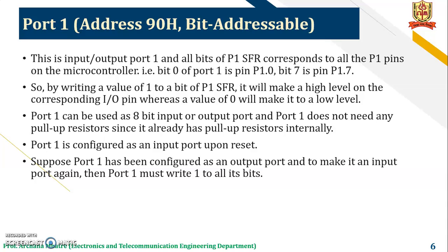So by writing a value of 1 to a bit of port 1 SFR, it will make a high level on the corresponding input-output pin, whereas a value of 0 will make it a low level. Port 1 can be used as an 8-bit input-output port, and port 1 does not need any pull-up resistor since it already has a pull-up resistor internally. Port 1 can be configured as an input port upon reset. Suppose port 1 has been configured as an output port, and to make it an input port again, you must write 1 to all the bits. That means all the bits of port 1 should be 1, high.